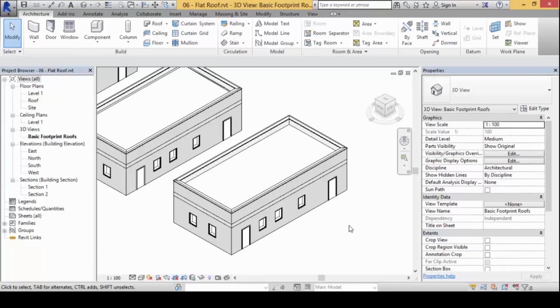Flat roof. It's called a flat roof because it looks like it's flat, but again in reality a roof is never ever flat, even though we call it a flat roof, because we simply cannot afford to allow the roof to become a swimming pool. In a thunderstorm situation, if the roof is flat, the water does not move. It stagnates there, it builds up.